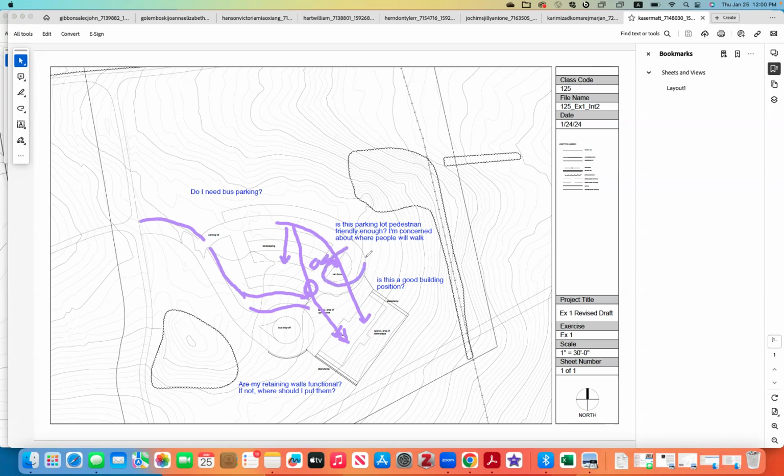Yeah, this area seems a little dangerous to the pedestrian. Let's see. We're turning around. So your island would actually be here because you're directing people to turn around. The major turning direction is here. Okay, and then does it make sense? So this is the driving aisle. I'm outlining the driving aisle. You want this driving aisle to flow pretty well.